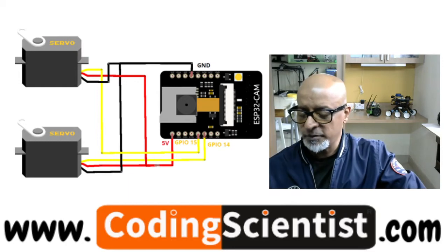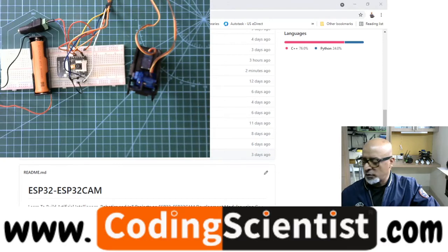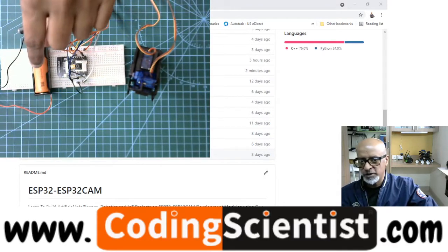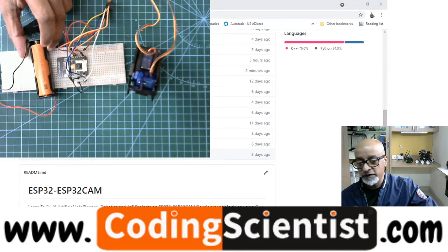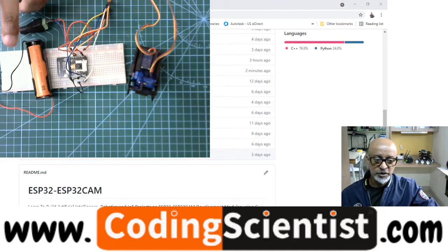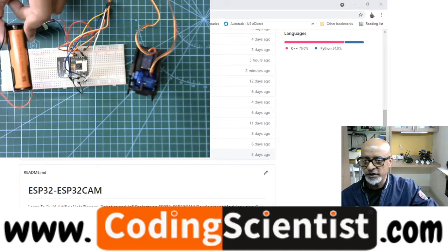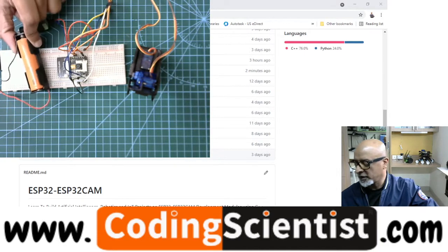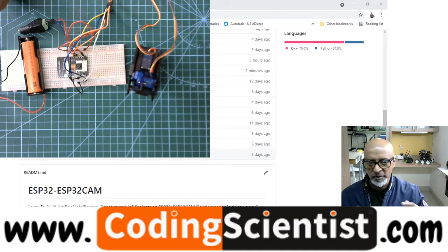The way I had built, let me show you my circuit the way I had put together. So this is how it looks. I just put a temporary structure on the breadboard to test it, and make sure you are using a 3.7 volt battery, guys, because we will not be able to hook up your ESP32 cam with the FTDI board once you build the circuit, right? So you have to power up through the breadboard and use this kind of 3.7 volt 18650 battery. Do not power up more than 3.7 volt. Maximum you can give is 5 volt. Do not increase that, you might end up damaging your board.